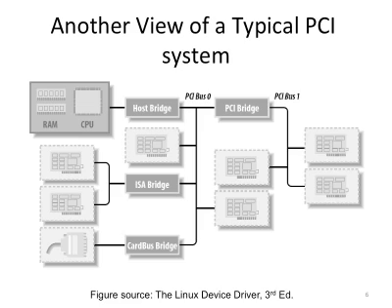This is another view of a typical PCI system, very similar to what we just saw. This is the CPU and RAM. We have a host bridge, and this host bridge is often implemented as a chipset. If you've heard of the term chipset, that's the combination of a number of different controllers inside the same chip, and the chipset connects the microprocessor and other interconnection systems. In this example, it's a PCI bus. Between PCI bus 0 and PCI bus 1, we can have a bridge to interconnect them. And on these buses, these are the different devices that we can connect.